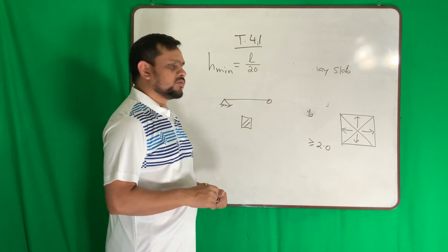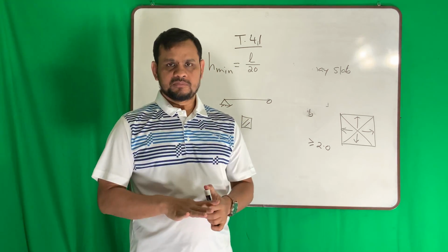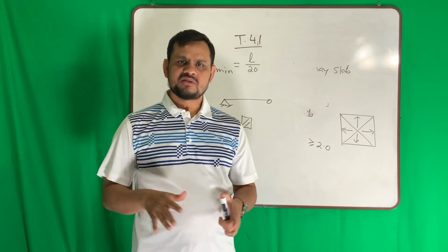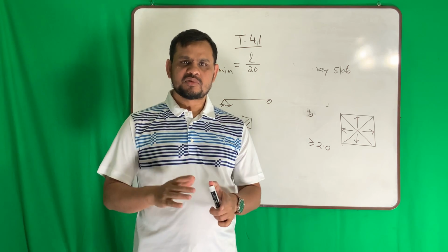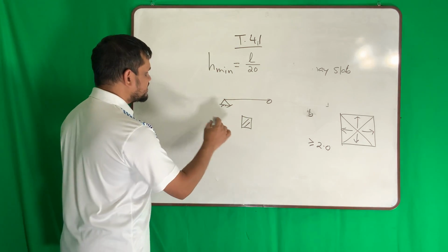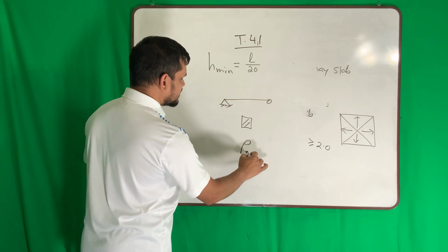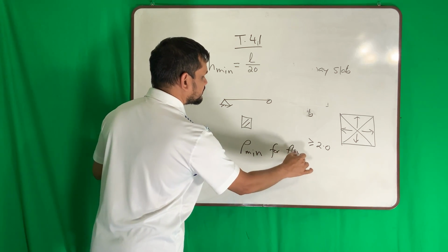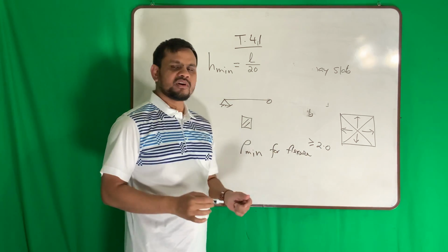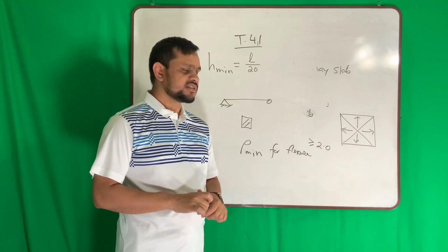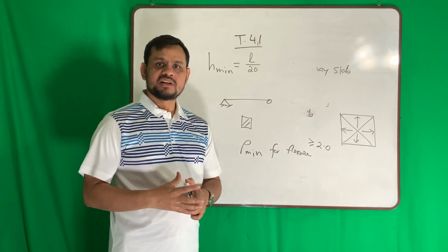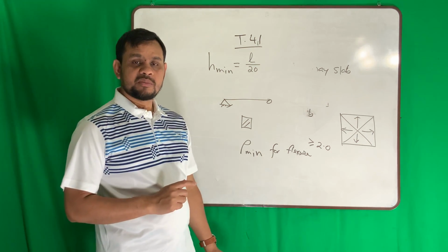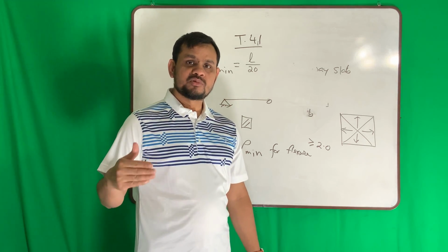Okay, concern number 2. The load on a slab is very small because there are so many beams, and inside the beams the slab length is not so huge, so load on slab is very small. So minimum reinforcement is a concern. So rho min for flexure is a concern. In most cases, the steel required may be less than the minimum recommended for flexure. So check it. Whenever you calculate the reinforcement, make sure it is more than the minimum.